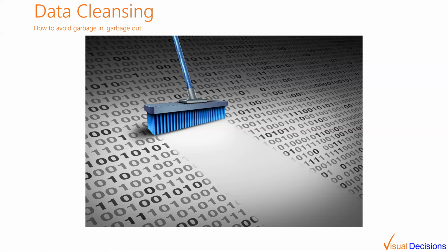But you still may need to get information from your people. Just an example there is, when you have an e-stop, e-stop as a fault code doesn't tell you much. And you may not see anything in those process variables that tell you why the e-stop occurred.